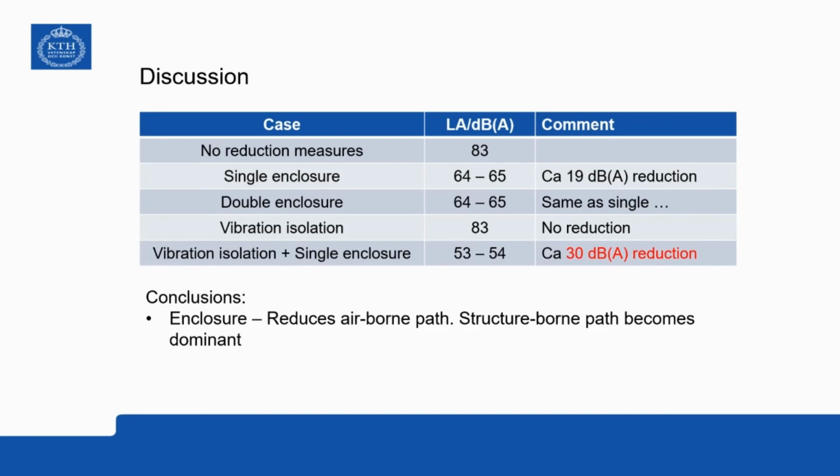And the plate and tabletop, because they vibrate, they will also emit noise. And that is the structure-borne, the vibration-borne path. And this contribution becomes dominant over the remaining airborne path. So in order to improve the situation now, we must reduce the structure-borne path.